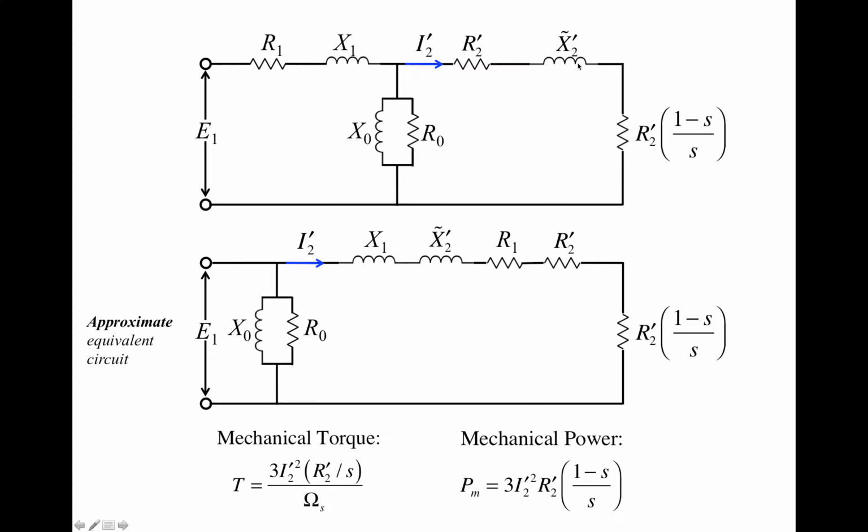If you look at this particular branch, it's 3 components connected in series. So you first obtain the equivalent component for this branch, and then connect that to these 2 branches in parallel, and then get the equivalent component for these 3 branches connected in parallel.